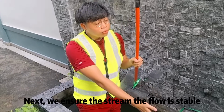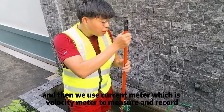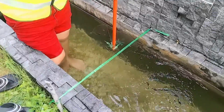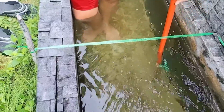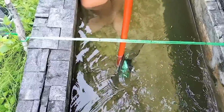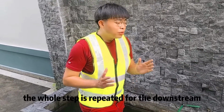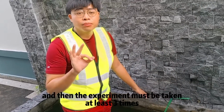Next, we ensure the flow is stable, and then we use the current meter, which is the velocity meter, to measure and record the average flow velocity in each subsection. The whole step is repeated for the downstream, and then the experiment must be taken 3 times.